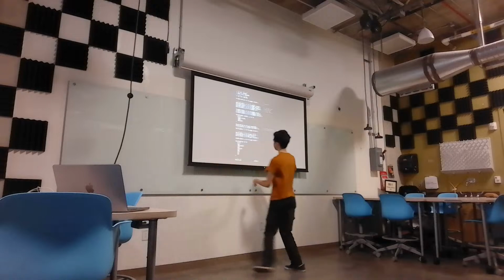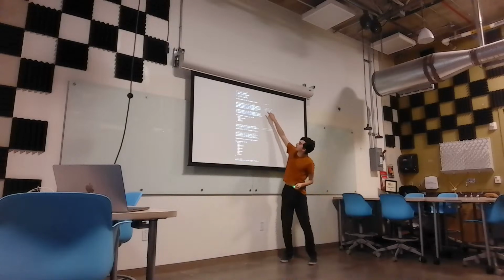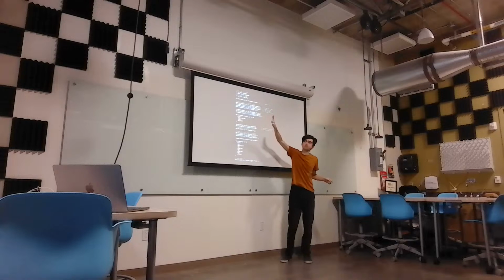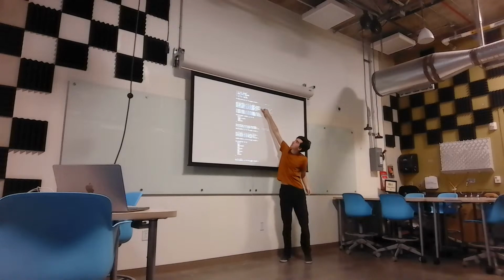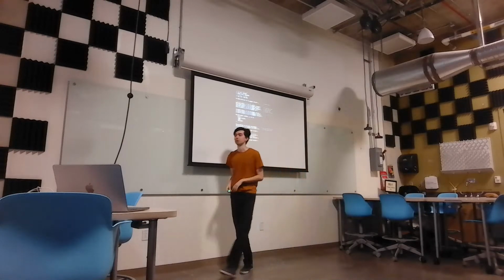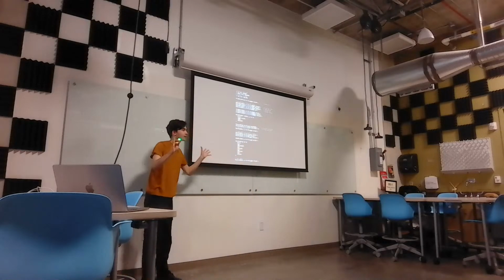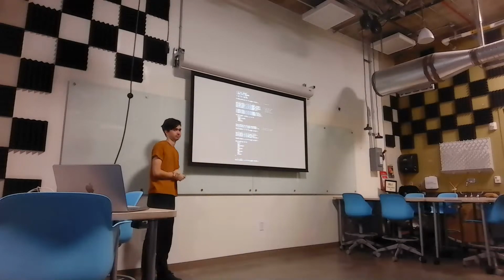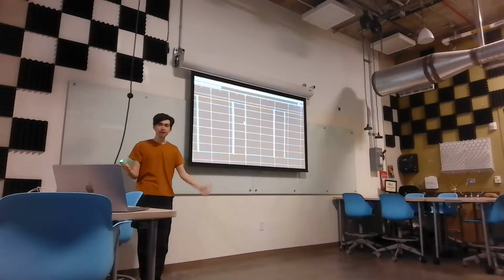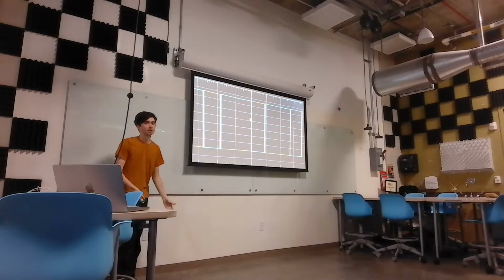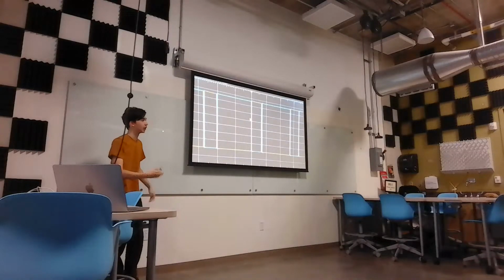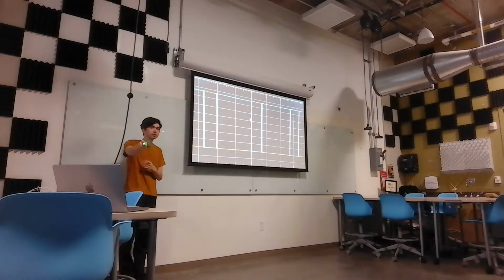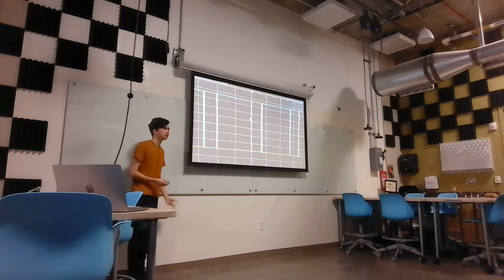Let's look at one that's easy to understand. Here, I'm saying this pin is floating. Then I say it's now an output push-pull. Then I put it in alternate mode, and then the second alternate mode. It's crazy wording, guys. You don't need to fully understand it. Just understand, I configured a version. Check it out. Look at that. The orange signal is channel 1, and the blue signal is channel 1N, the negation, the not of it. That was crazy. I just made a microcontroller do my bidding just by putting some bits in just the right places.